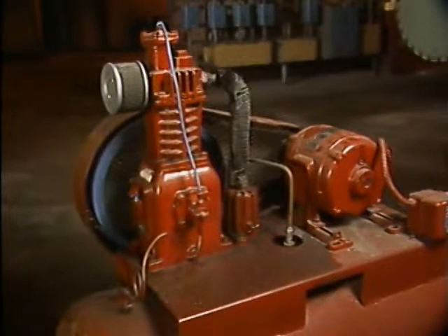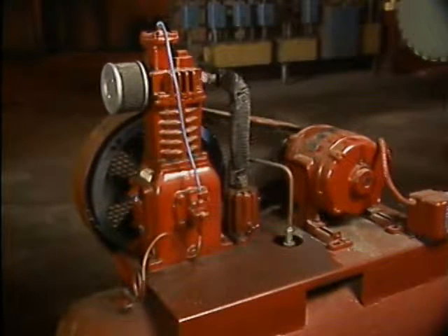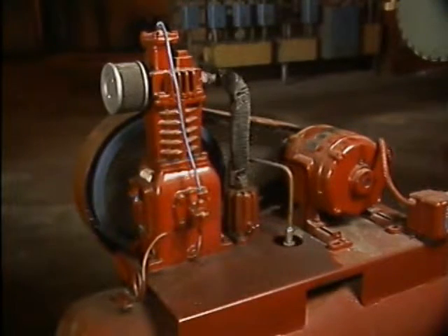To keep the pressure from rising uncontrollably, some method of regulating the pressure must be used to control the amount of gas that is delivered by the compressor. Pressure regulating methods range from a simple on-off system to more sophisticated methods, such as the use of inlet valve unloaders. When pressure is regulated by a simple on-off system, a sensor in the receiver controls the compressor's drive mechanism. When the pressure in the receiver increases to a preset value, a signal is sent to stop the compressor. When the pressure in the receiver drops to another preset value, a signal is sent to restart the compressor.